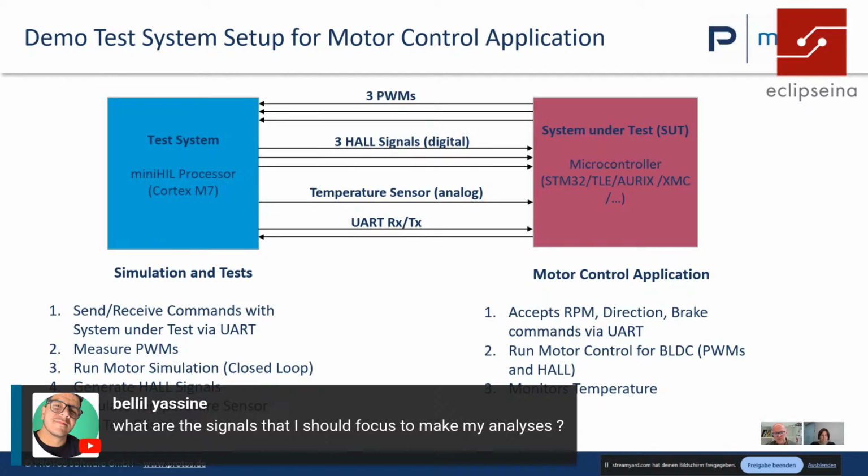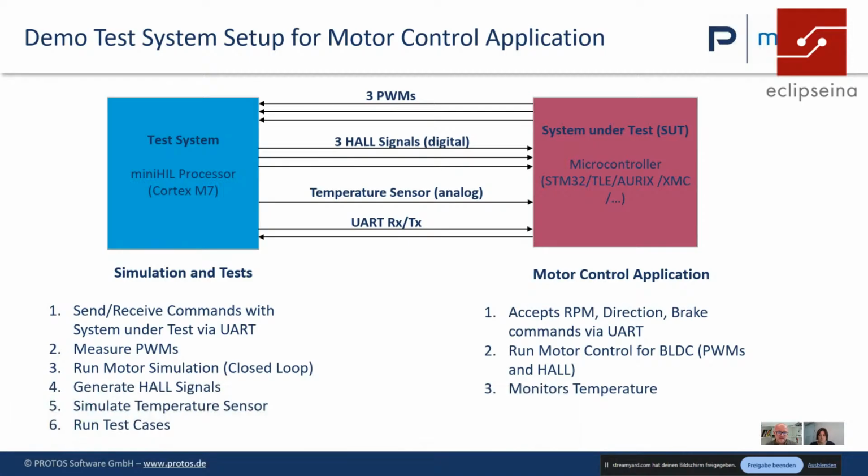So for example, if you have a CAN bus, a LIN bus, and a UART attached to this ECU, and in this variant of your microcontroller system you only use the UART, then you only need to use the UART for testing. I hope this answers the question a little bit. But you do not get away with just simulating the 3 signals you want to test, because your system actually needs to work.